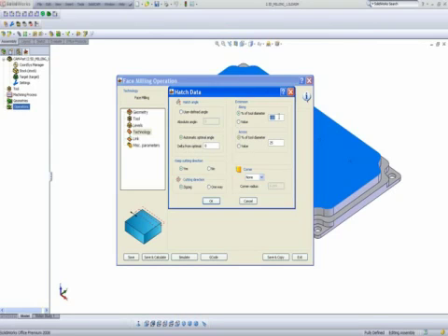If I were to change this to 50%, then the center of the tool will come exactly up until the border of the part. In this particular case, I would prefer 110, as that would allow the tool to actually leave the part itself and then go back around. Now, we also have how much do I want to go past the part on the side.